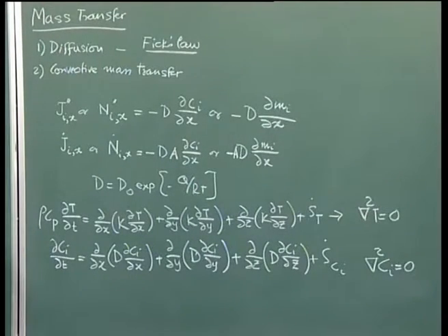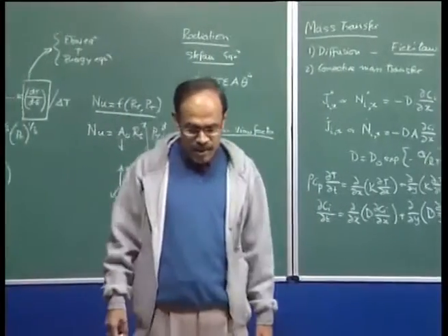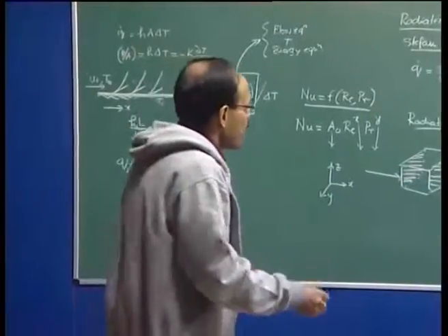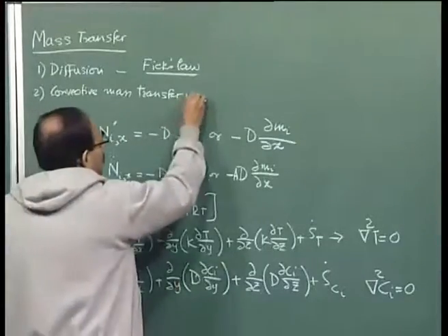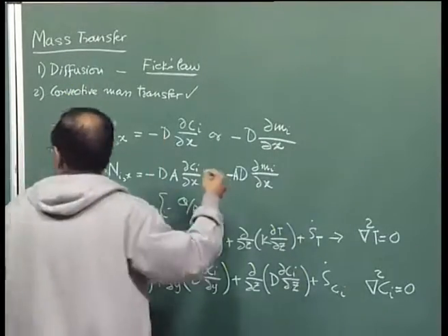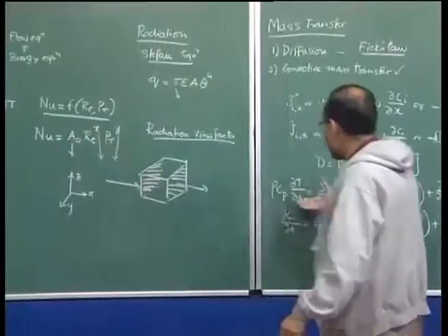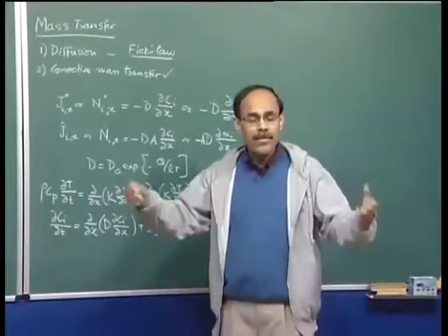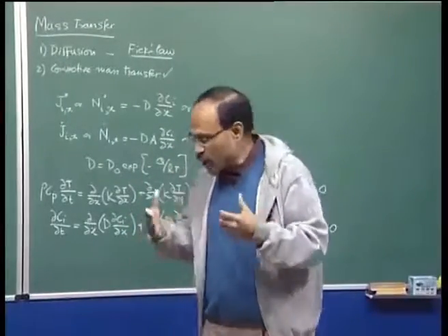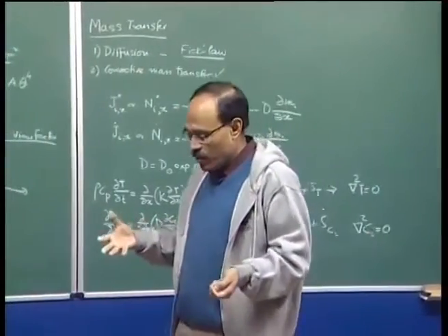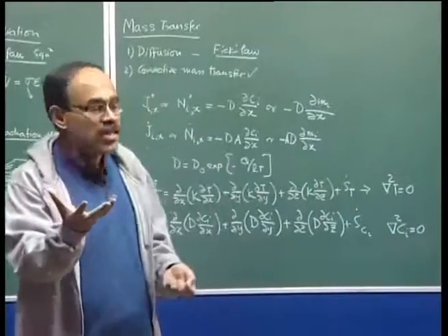Now, coming to convection, again we have the same kind of equation that we have seen in the context of heat transfer, when you try to calculate convective mass transfer rates. As for diffusion, the rate of diffusion would be relevant, just like the way I gave you the example of ingot heating to explain the relevance of heat conduction. Mass diffusion could be completely relevant, or totally controlling the mass flow, for example the flow of carbon in a coke structure or in a casting.